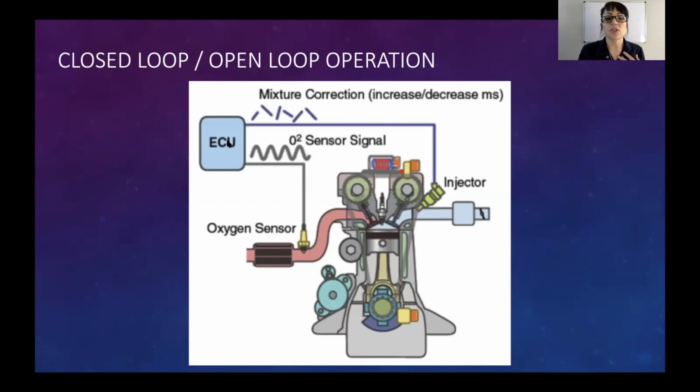That signal goes to the ECU. ECU says, oh, all right, that was too rich. It adjusts the injector signal, does it again. O2 sensor says too lean. It goes back and forth, so on and so forth, over and over in its closed loop operation. Input, process, command, input, process, command, over and over until a couple of things happen.